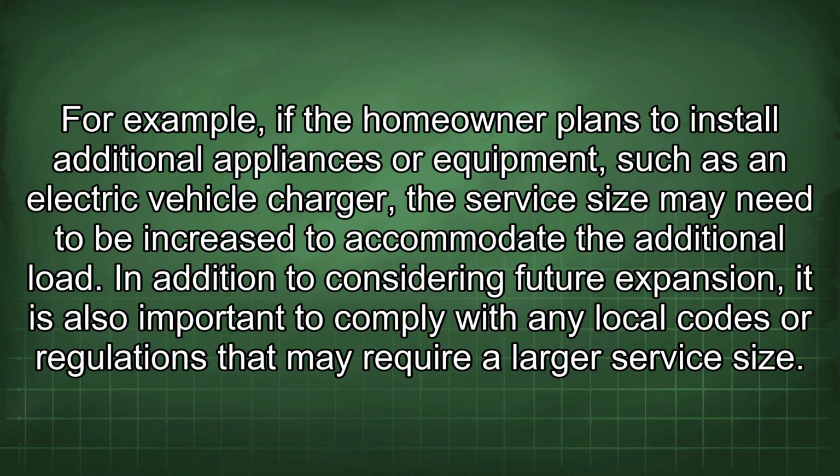For example, if the homeowner plans to install additional appliances or equipment, such as an electric vehicle charger, the service size may need to be increased to accommodate the additional load. In addition to considering future expansion, it is also important to comply with any local codes or regulations that may require a larger service size.